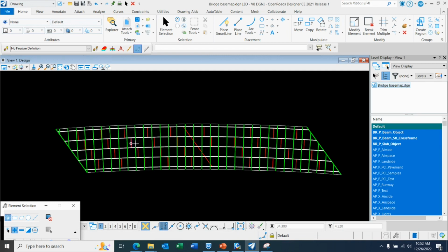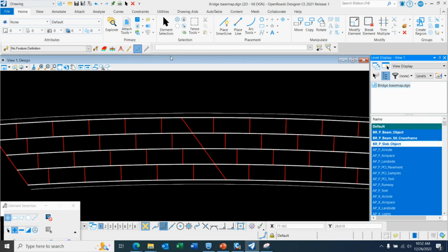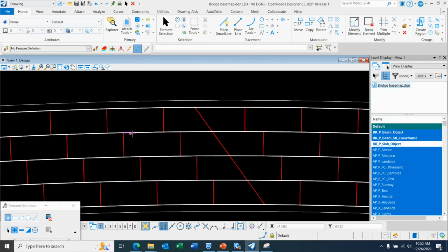One thing that I forgot to do earlier is to group my beam portion in the negative moment region. We need to select the portion of the beam that's going to use different section and put it in a different layer so that it's easier to assign section once we import this CAD file to Midas. For this, we'll turn off the cross beam and look for that splice location. We created intersection node at the very beginning. If you remember, it's right here.